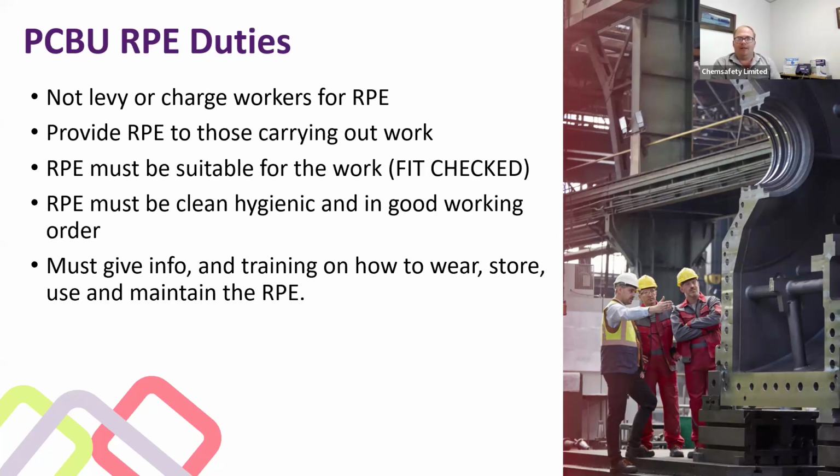You need to provide that RPE to those carrying out the work in those hazardous environments, and that RPE must be suitable for the work. So that means it's got to be fit tested, sorry. It's got to fit the worker. It's got to be not causing them pain, discomfort, all those sort of things. It's got to be in working order. The RPE must be clean and hygienic and in good working order. So there's no point giving them someone's old respirator. It's a bit gunky, moldy, filters a bit cracked or damaged, missing seals.